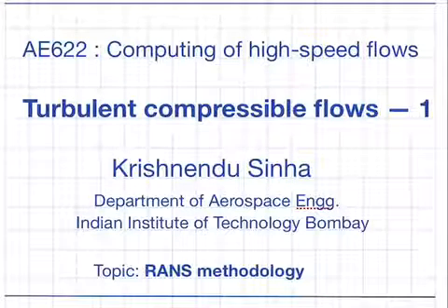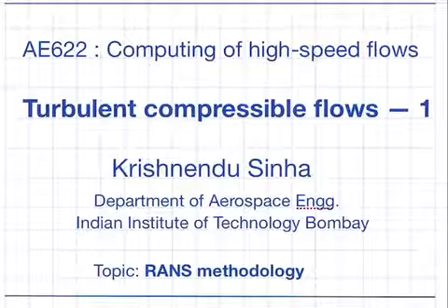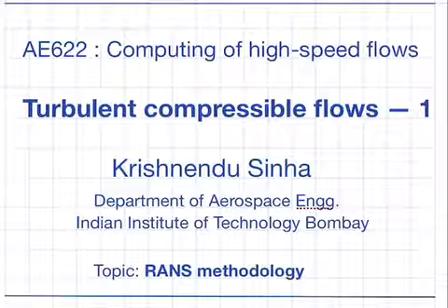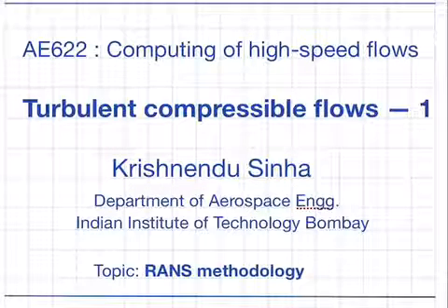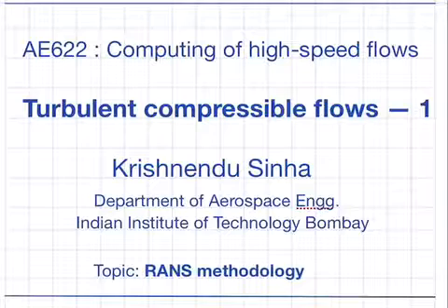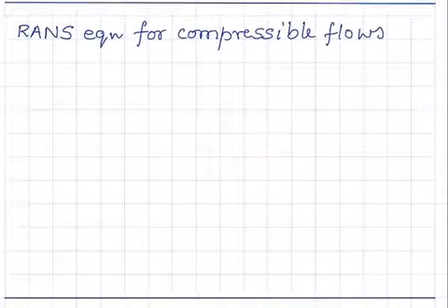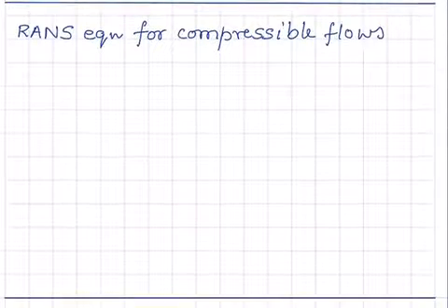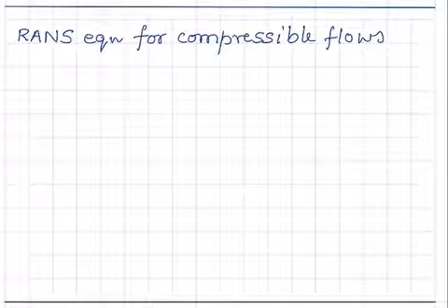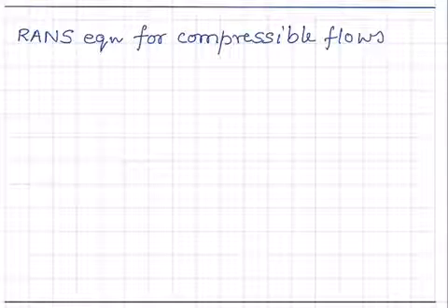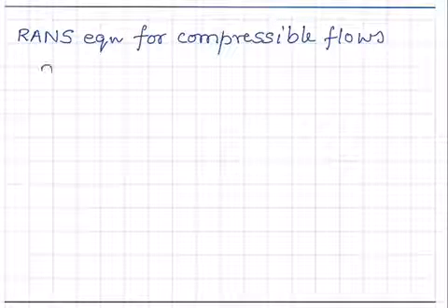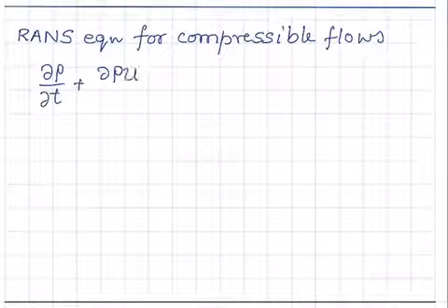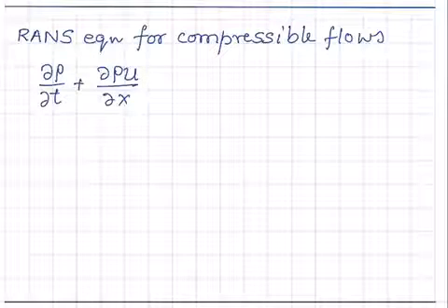Today's lecture is about how to compute compressible flows that are turbulent, and we will focus on the RANS methodology, Reynolds averaged Navier-Stokes equations. So let us start with the governing equations for compressible turbulent flow. We will write the mass conservation equation in this form, which we are familiar with from earlier.